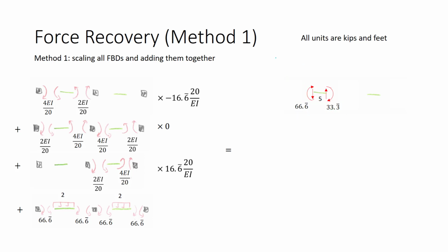One more aspect to mention here. The rotation for degree of freedom 2 was a negative, and you'll notice that this moment is drawn on the member in a negative moment direction. But when I take that and draw it over here and incorporate the negative sign, I'm now showing this moment in a positive bending direction. So we see how the sign of the displacement influences the answer.